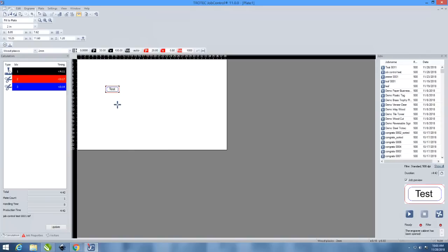So you can see here we have an engraving icon and some scissors for the cutting icons here. Engraving is going to take 4 minutes and 11 seconds. Cutting, our red lines are going to take 17, blue 14 seconds. It does seem a little long to me. You can see down here the update button is flashing. That means it was still calculating. So keep on pressing this update button until it stops flashing, and you should get a pretty accurate time of how long your job's going to take. Once you know how long your job's going to take, you can now quote your clients if they're asking for hundreds or thousands, hopefully, then you can quote them on how long that should take.